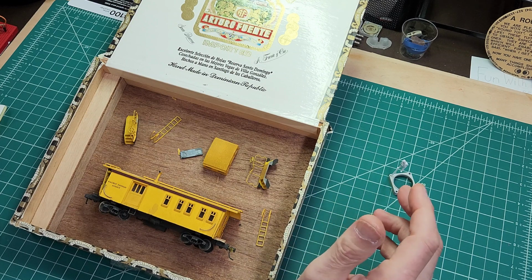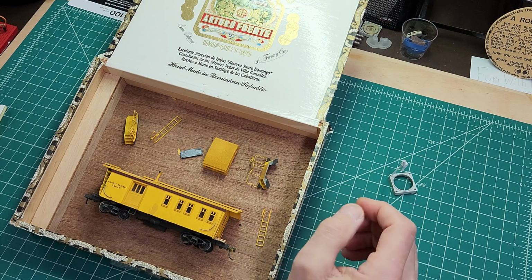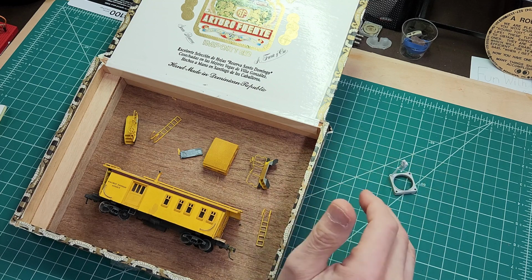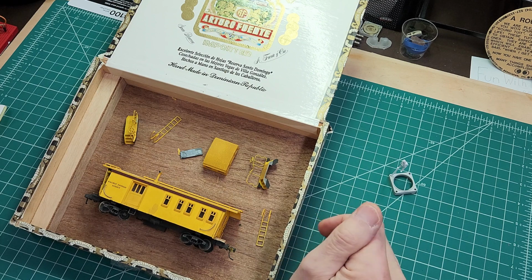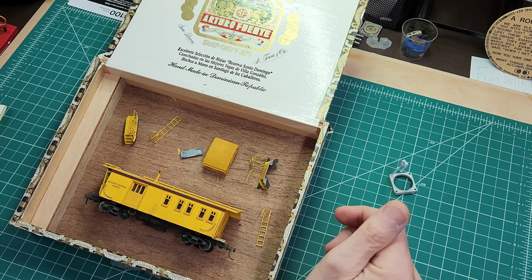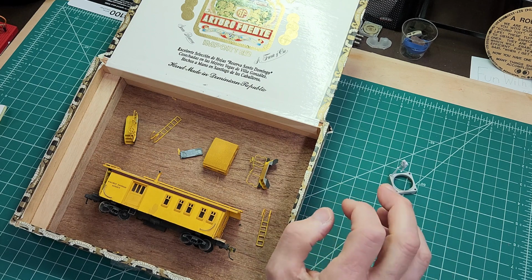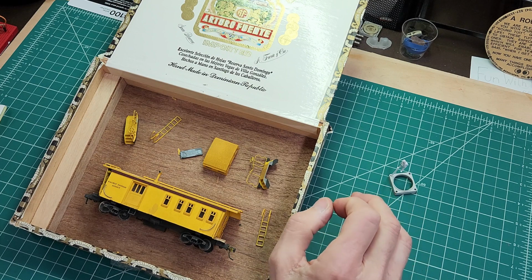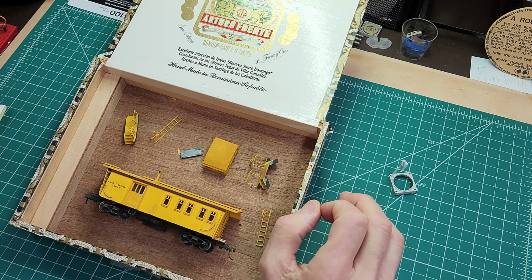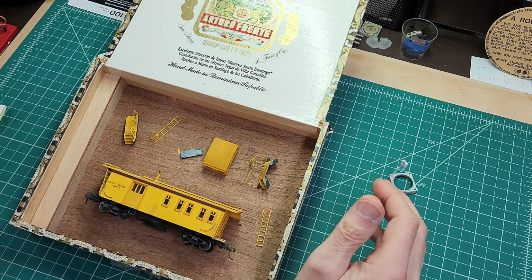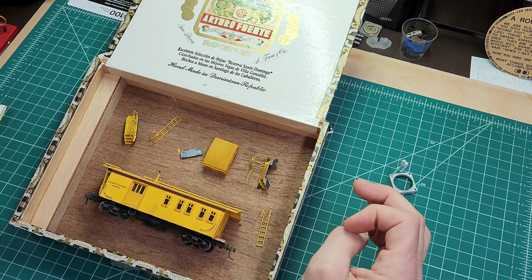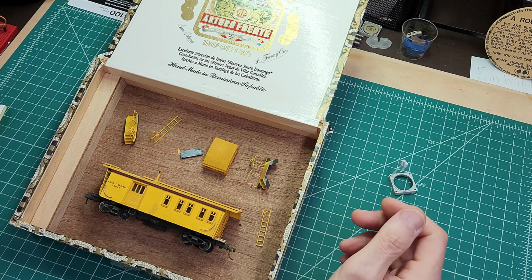And as you recall, I went through all the process of using a voltage divider in order to make that happen. When the attachment is detected by the chip, the task method state machine proceeds to read the device configuration data via the USB endpoint 0. That's, as I stated, the control endpoint. That data also contains the endpoint descriptors.